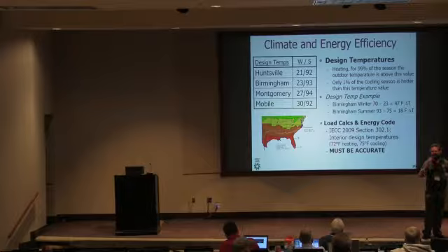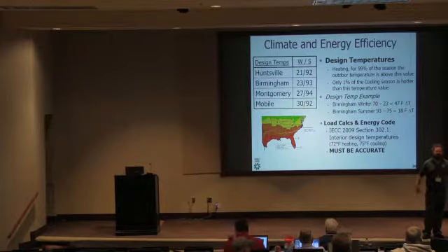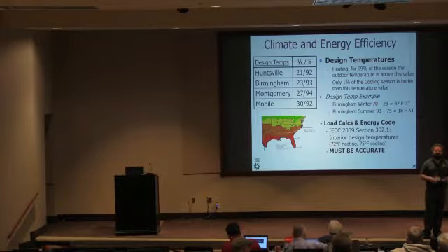If I was foaming a crawl space house, I would really consider a closed cell spray foam on the underside of that floor because it's an air barrier, it's going to stay in place, it's a moisture barrier, and there's a lot of ground moisture. We're supposed to put plastic down, but a lot of times existing homes don't have complete plastic coverage. I would still do that. But if I was going to foam a house and money was no object, I would not only foam the roof line as a retrofit, I would do a closed cell spray foam on the underside of the floor in a crawl space, and that's going to help a lot because then you can just vent that crawl space with an active exhaust vent, and you're going to really mitigate the potential for radon issues.